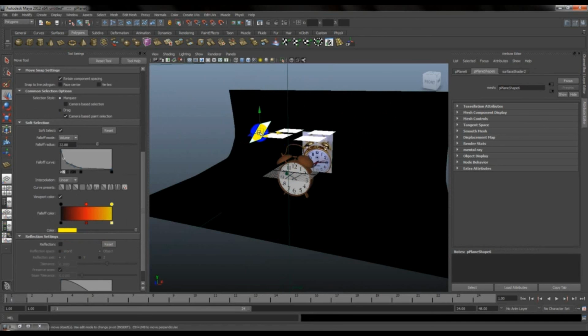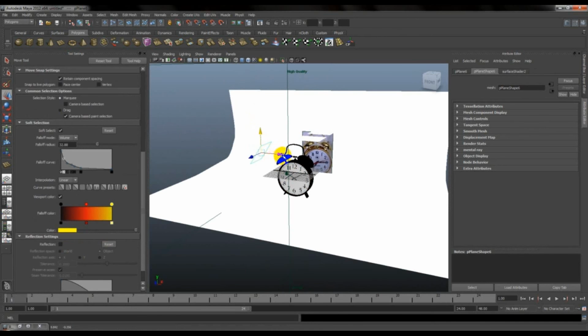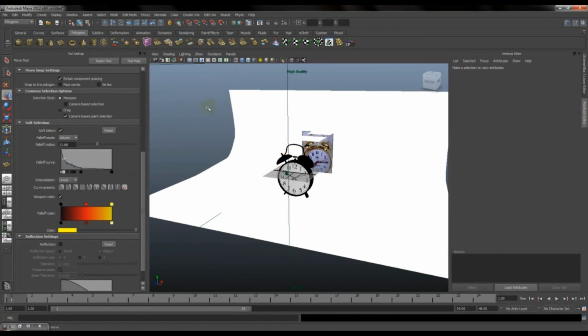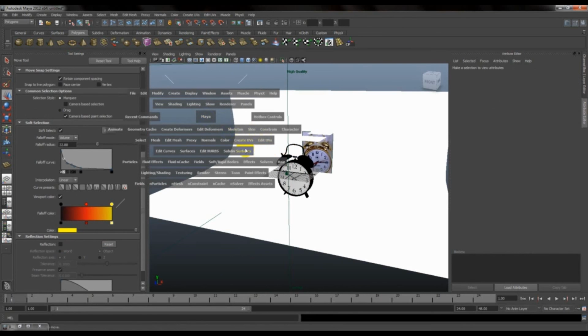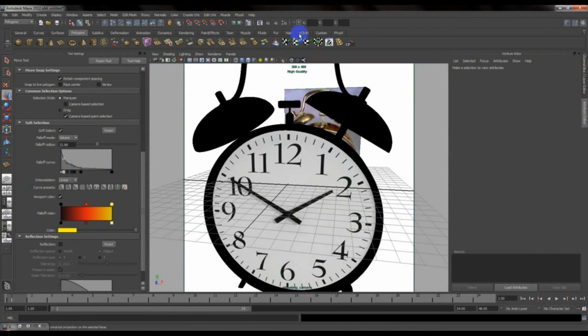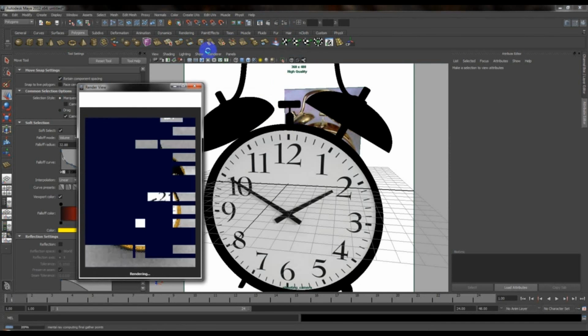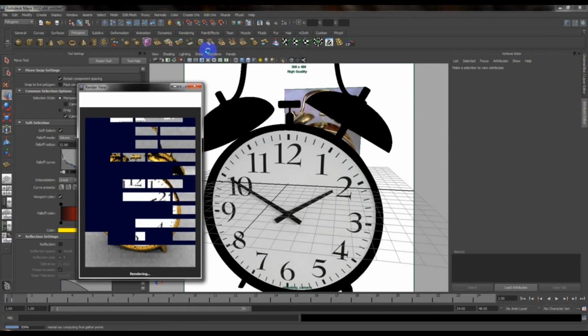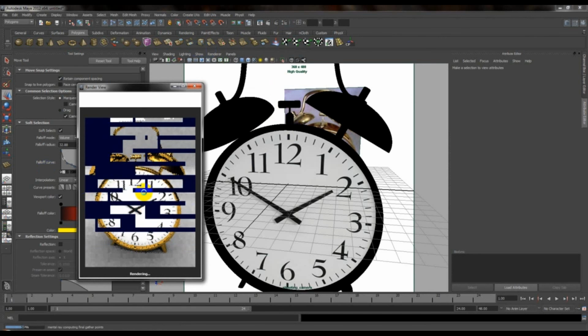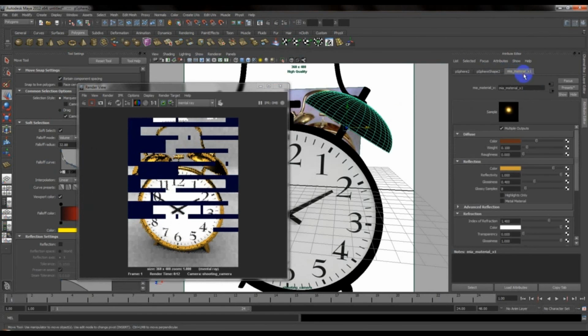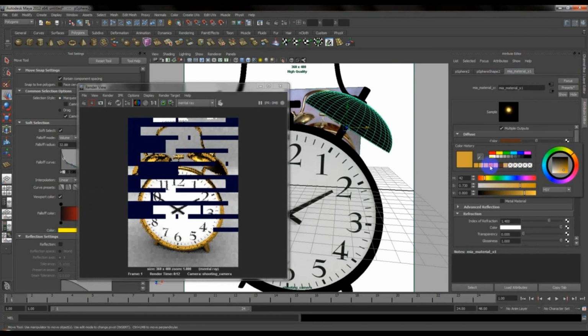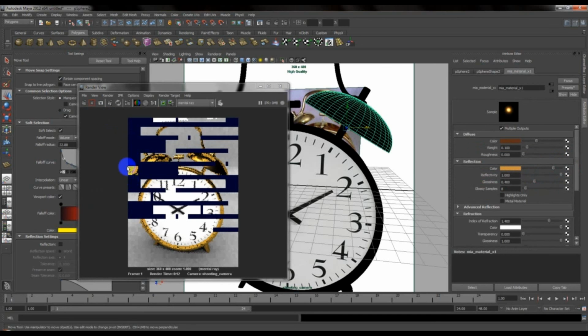And after that, I'll go to the high quality rendering to see it. If you select high quality rendering, it will be all white. After that, let me go to the panels perspective and go to my image, make a render of it, and let's see how the new result will look after putting these surfaces. These studio lights, these images that I've made with the surface shader of white, are actually, with final gathering enabled, going to act as a light source.